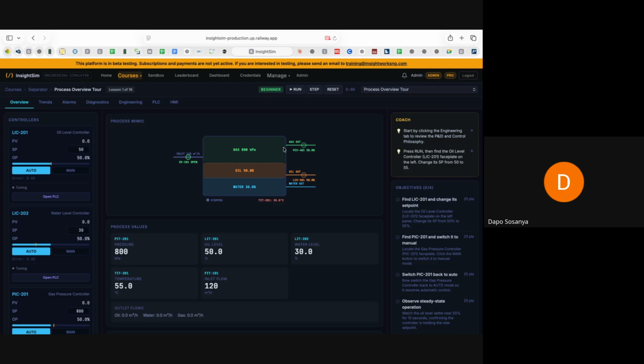We want to separate it so that we can either send it to the flare and burn it off, or send it to a compressor station and perform further processing on it. So everything comes in as one inflow, and then we have 3 outlets from this one tank. For those 3 outlets, we must take care of water, of oil, and of gas.